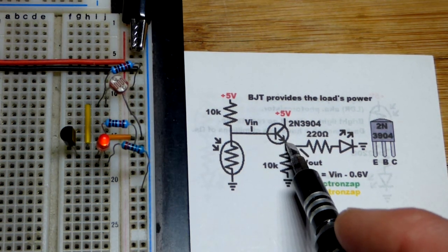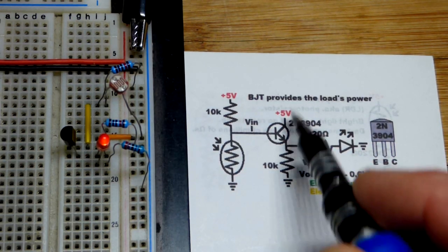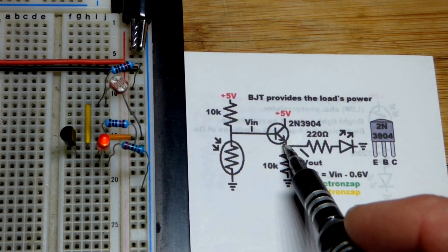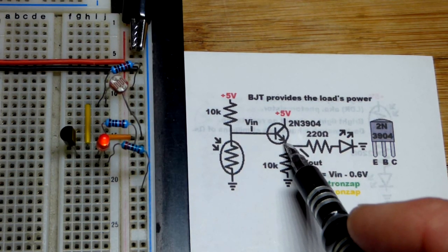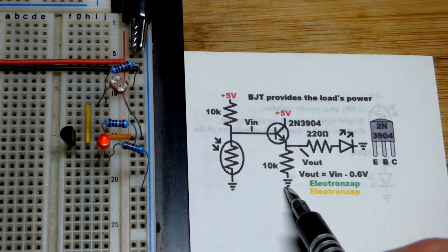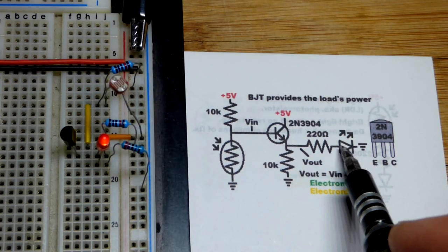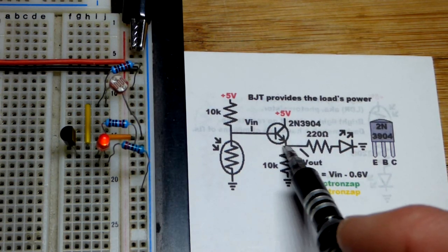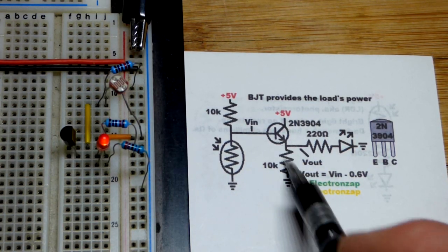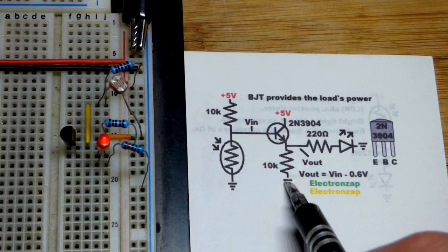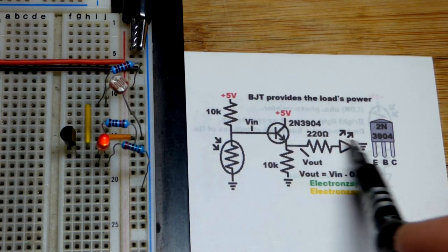We have the emitter right there. So always remember, you need a little bit of base to emitter current to flow for a much larger collector to emitter current flow. Along the path we have first the load, but also a helpful 10K resistor. You may not need the 10K resistor, but it's usually good to add it, especially when you have diode drops that drop a certain amount of voltage. Sometimes that can confuse the emitter as to where ground is. But with the 10K resistor, it does a pretty good job of setting a voltage across the 10K resistor based on ground, rather than whatever load may have confused it otherwise.